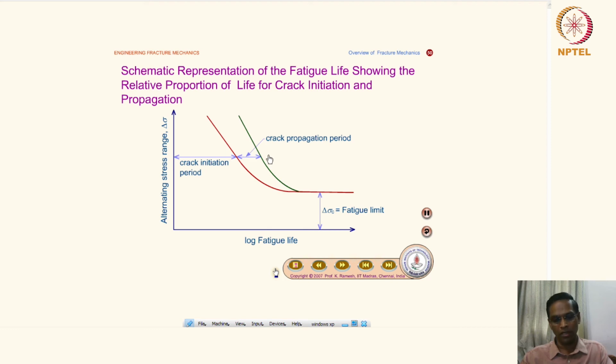So very important. As the stress range comes down, the crack initiation period keeps on increasing. So what is important to note is that the majority of the life of the component is spent on the crack initiation period rather than the crack propagation period. Okay, this is something very important. So that's why it is brought here.